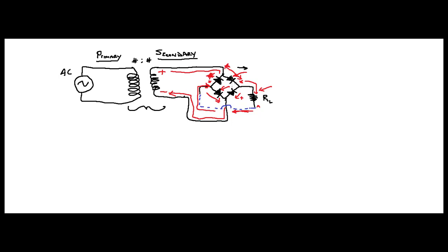So think about that. What you're interested in here is, where do I have it here? Do I have it right here? Here it is. Your peak voltage output is going to be your peak voltage from your secondary, which is between these two points, minus 1.4 volts.